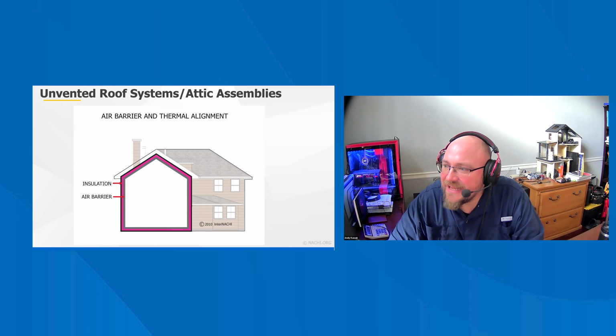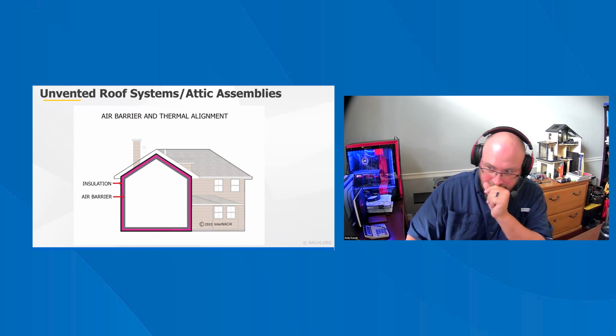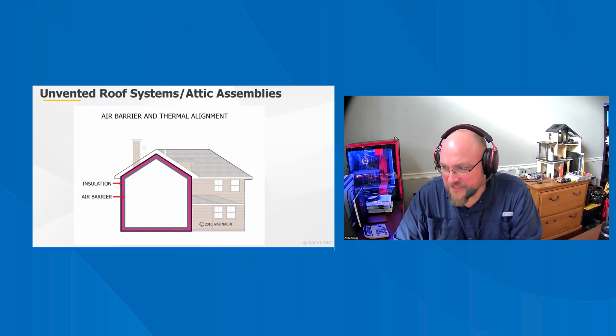To control air tightness, an air barrier system must be installed in the roof insulation assembly. An air impermeable layer may be installed on the inside of the air permeable insulation, such as fiberglass or cellulose, to control both air and moisture movement. For roofs sealed with spray foam insulation, air leakage is effectively stopped. Failure will be likely via accidental or unintended airflows at unvented wood framed pitched roof systems, such as around roof penetrations, including plumbing vents.